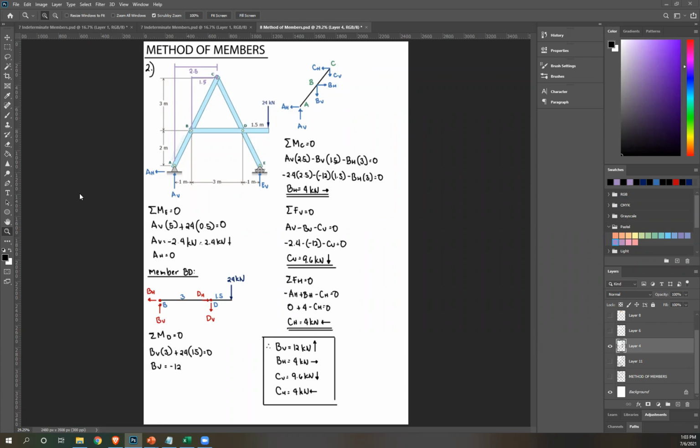When you're drawing your free body diagrams, whichever you start with, that is where you're gonna base everything else. I started here, and then I drew the opposite here. So even though I got a negative here, I'm still gonna follow this. Again, you have two choices. You can just keep all of your drawings as is. You're not gonna change anything. Just remember to follow the correct order of your free body diagram, meaning I started here, so the next one should be the opposite. You can start here, and then if you draw this, it should be the opposite of that. Just remember, again, to include the negative sign since you didn't change the sign.